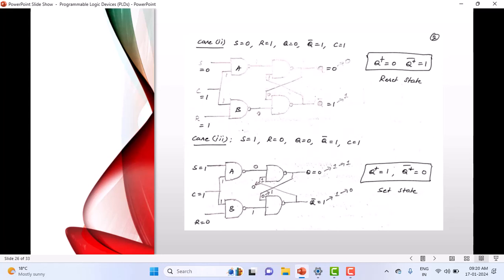And look here now, I assumed 0 and 1. Here I have stopped to see what input is coming. Now we look at this because I want to see what is the present state. So 0 and 1 is the assumed present state. 0 comes over here, already 1 is there. 0 and 1 gives you 1. 1 goes here, 1 and 0 gives you 1.